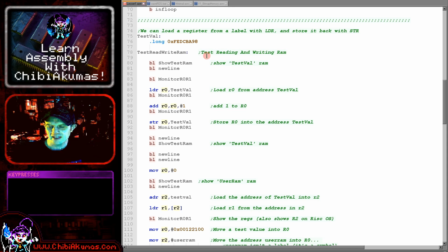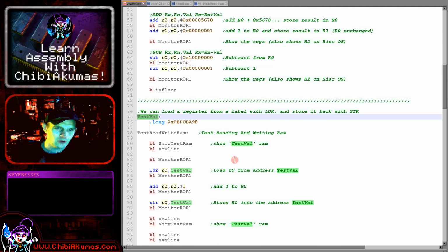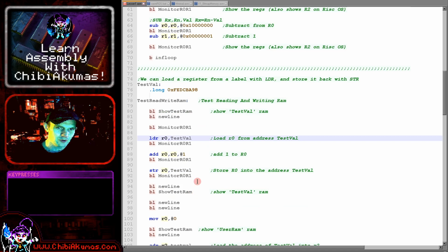Now with the ARM processor, there's two ways we can work with memory. In limited cases we will be able to use immediate values if the memory we're working with is nearby. But in the same way we can't load very long strings of hexadecimal into an address, we can also only address relatively nearby pieces of memory directly, without using another register to store that address into.